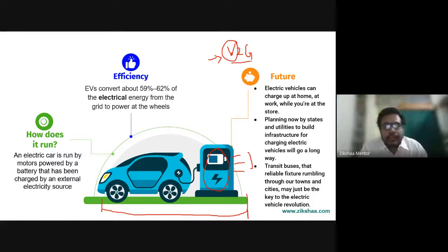And also we can talk about the second life of electric vehicle batteries, because the performance of the battery degrades over time. There are measures which calculate the performance of the battery, like, let's say, state of health. We can talk about that, what is state of health and state of charge, a little bit once we go into those details. But let's say there is a performance parameter called state of health, and every manufacturer recommends that once the battery goes below 80% or 70% state of health, it is unsuitable to be used as an electric vehicle battery.